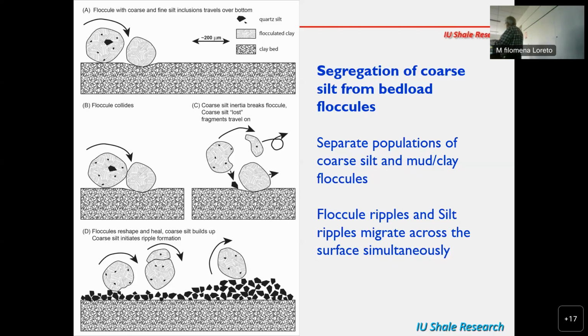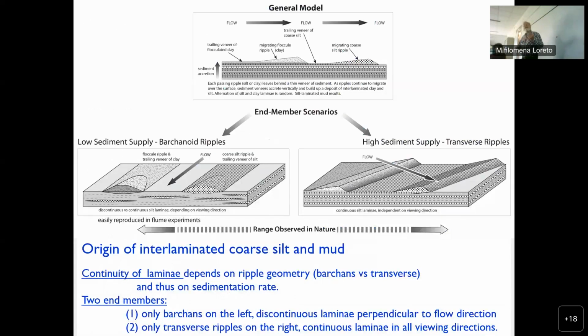Floccules are getting robbed of the coarse silt, and only fine silt and clays stay behind. So simply by transporting primary crudely sorted floccules around, we take the coarse silt out because it doesn't fit floccule structure, and it's bed load transported. And so we get something like this.